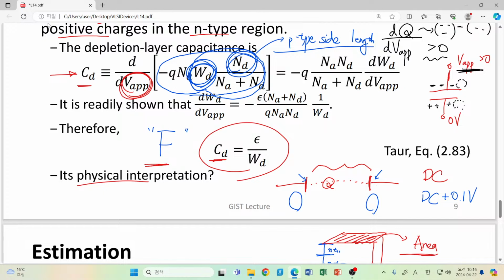At this point, we cannot generate more positive charges here or there, because our depletion layer has already completely contributed its capability. All of the movable electrons and holes are depleted, and in this depletion layer we have no further ability to change the net charge density. They are just depleted.